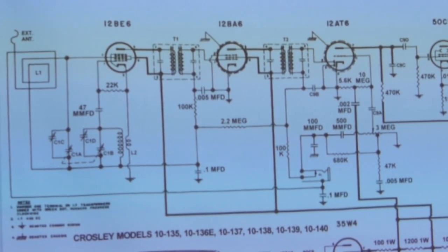And that signal varies negatively corresponding to the strength of an incoming signal or a radio signal that you want to detect. Now the beauty of the AVC circuit, of course, is that it's an automatic gain control, and the stronger the input signal, the more negative this becomes, and the more the negative bias turns down the gain of this particular part of the circuit. And this one too, because you'll notice there's an AVC going into the grid of the pentode for the IF amplifier.